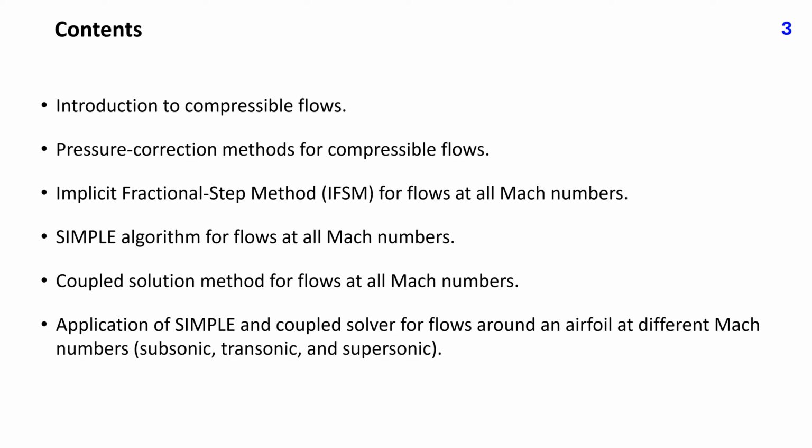The following set of slides is devoted to the SIMPLE algorithm for the computation of flows at all Mach numbers. SIMPLE and related methods for incompressible flows were presented in lecture 18. Here, the extension of such methods to compressible flows is described in detail. Most commercial and public CFD codes use such methods when computing compressible flows.